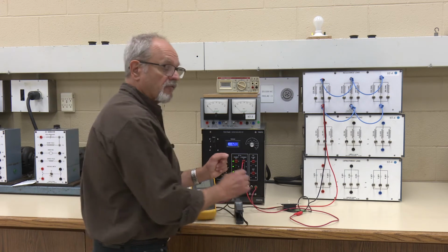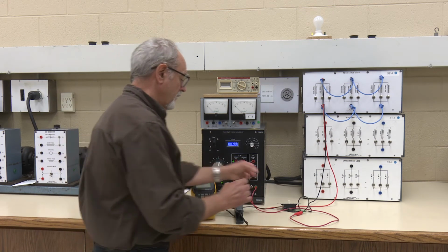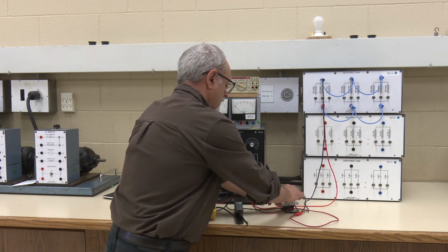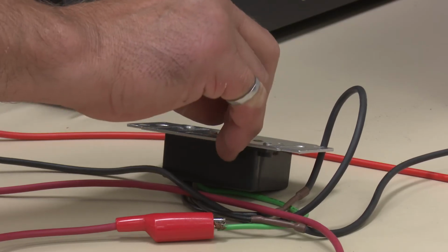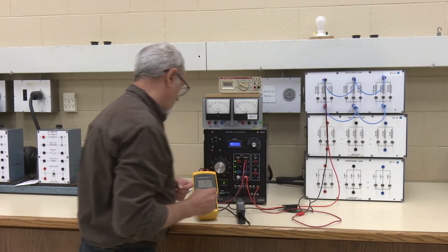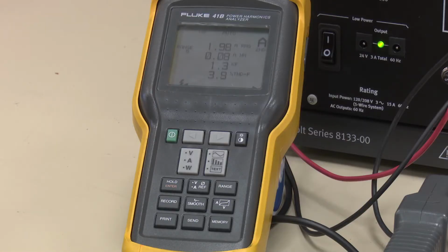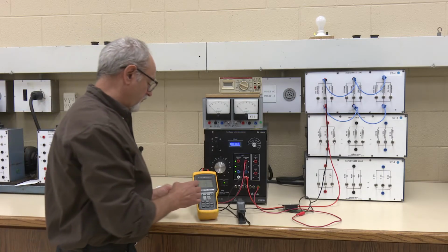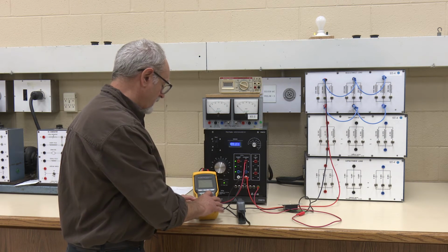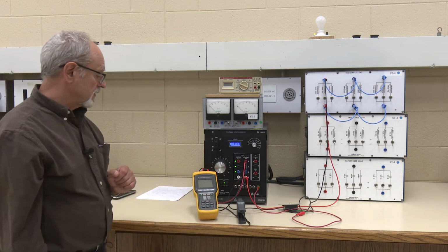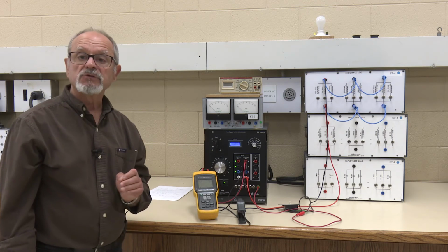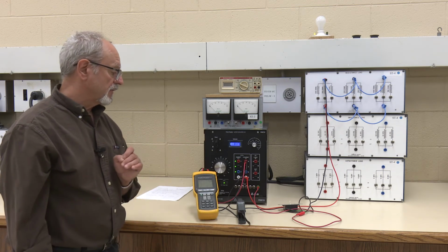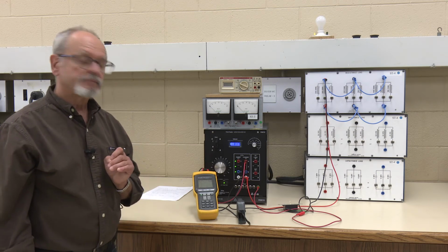So let's verify the current for an angle of 0 degrees. And we get approximately 1.98 amps, total effective current. Now, if we look at the current waveform, you'll be able to see that it's actually fairly sinusoidal. It's actually quite a nice sinusoid, which is what we expected because effectively there's no switching going on here.